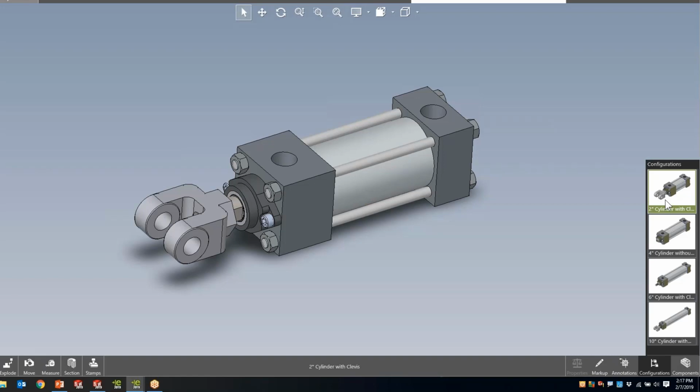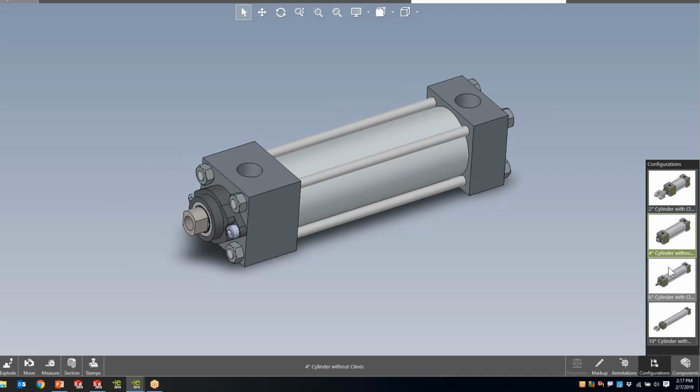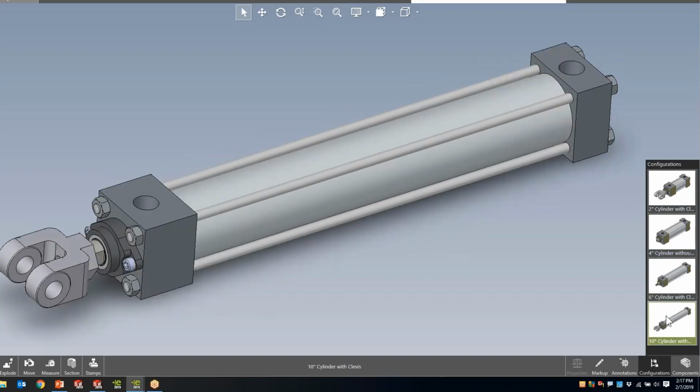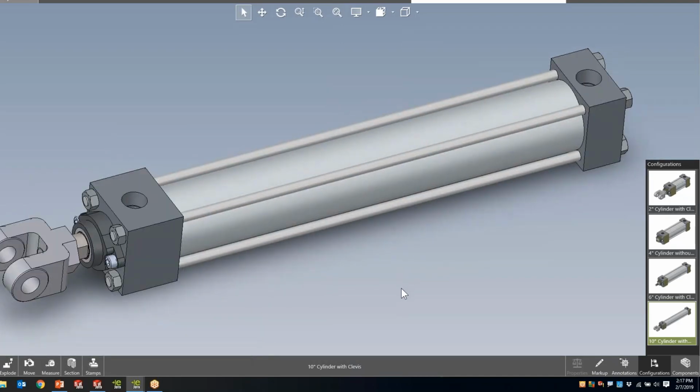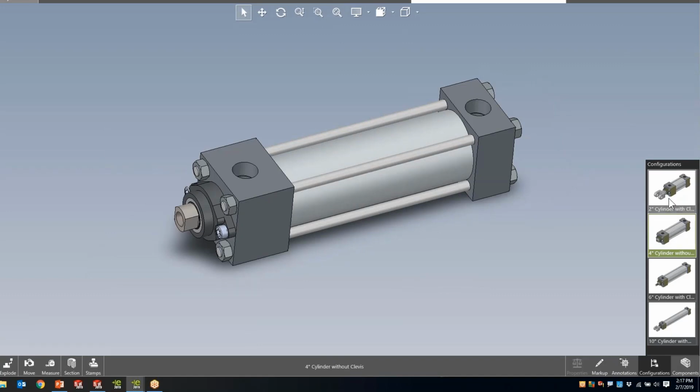Adding in that extra step to create an eDrawings assembly or an eDrawings part that would always need to be exported and updated. While we can add tasks like that into SolidWorks PDM, into our workflows, and even into the check-in process, having to have that extra file that needs to be maintained is definitely a hurdle for that option. So now with eDrawings 2019, being able to open a SolidWorks part or assembly, and as long as the correct options are set up in your system properties in SolidWorks, all those configurations will be visible.